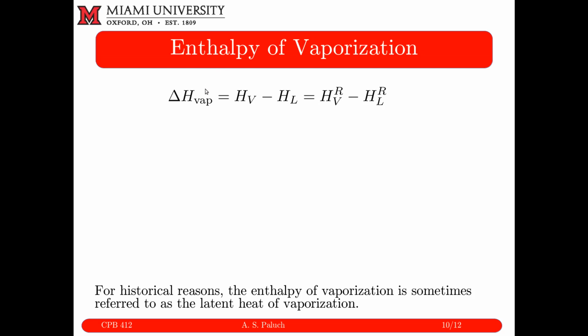And so what I'm left with is I could equivalently write this as the enthalpy of vaporization is just equal to the residual enthalpy of my vapor relative to the residual enthalpy of the liquid. Okay, cool. So the note here is for historical purposes.